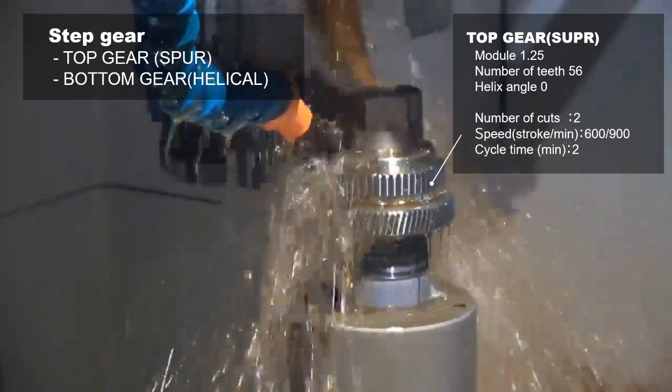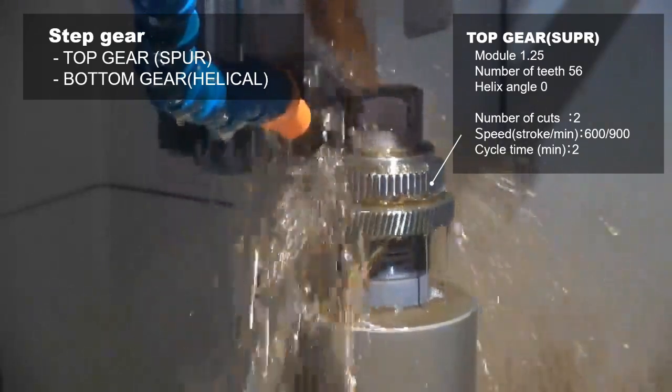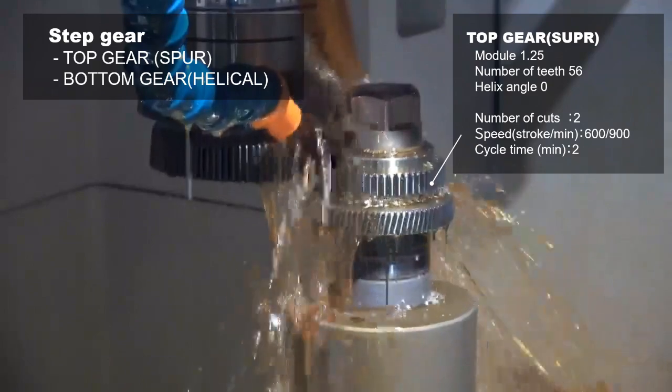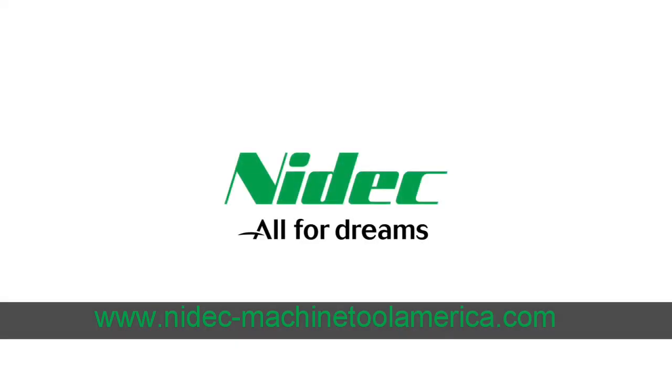In conclusion, the accurate calculation of the cutter stroke width is vital for the proper generation of internal gear and spline teeth. By understanding the calculation process to determine correct overtravel of the shaper tool and considering the specific requirements for helical and shoulder gears, gear design engineers can ensure optimal internal spline and gear production.